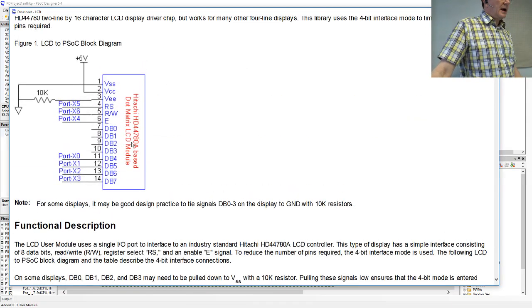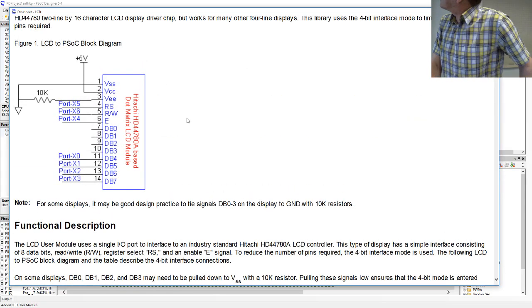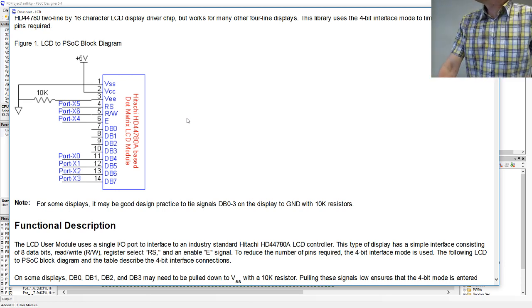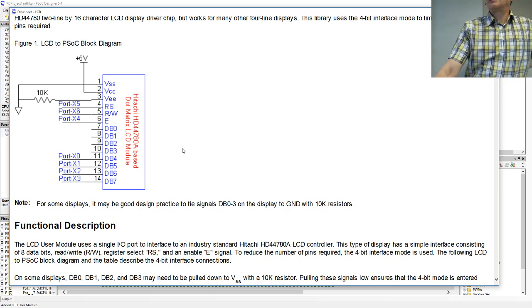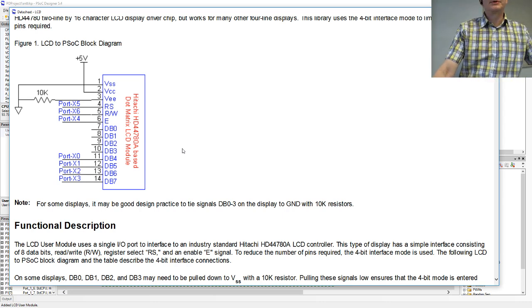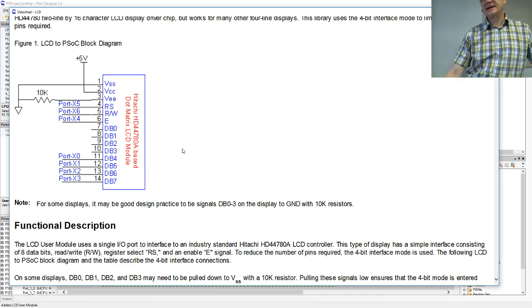And if you want to make your own circuit design, it also gives you the pins where they should be going. So after selecting the port, you need to do the wiring. On those design kits, we have the port pre-wired to the LCD port.